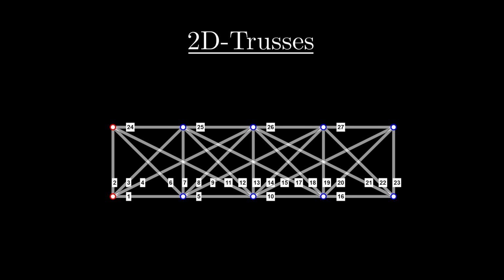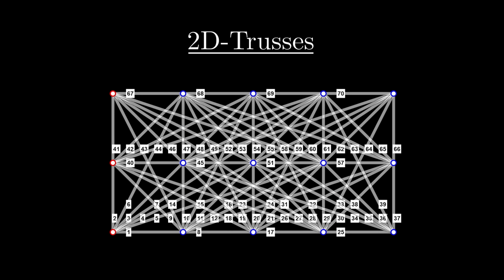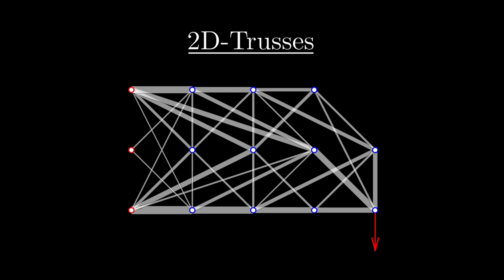The process here is always the following. Once we have constructed a desired ground structure and determined the force which will be applied to either one specific blue node or to multiple blue nodes, we will calculate the optimal distribution of the given material, which is obviously bounded, within the truss to achieve the maximally stable truss to withstand the considered forces.